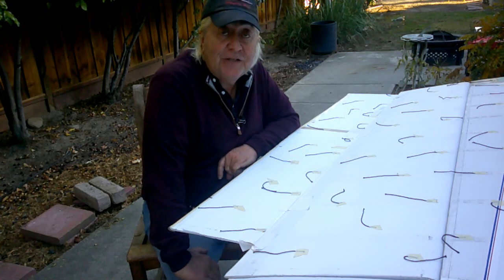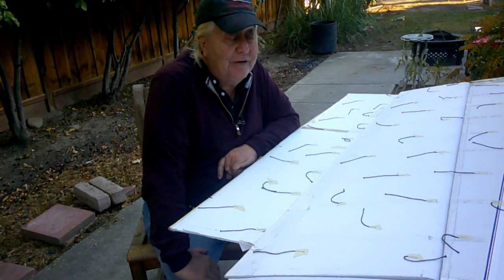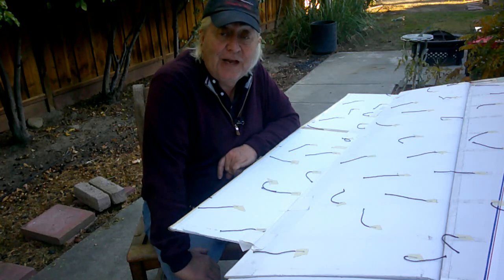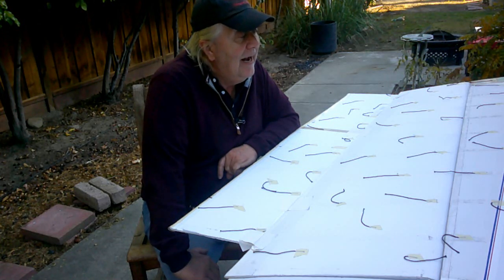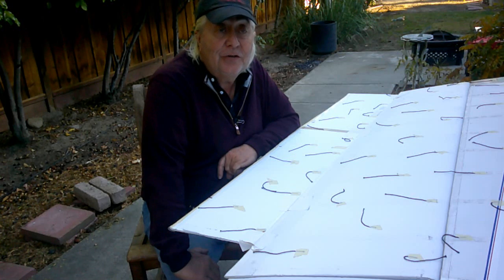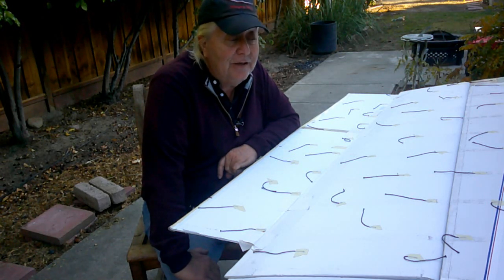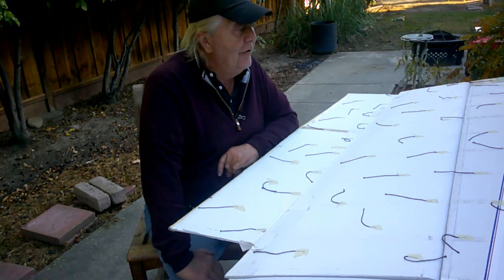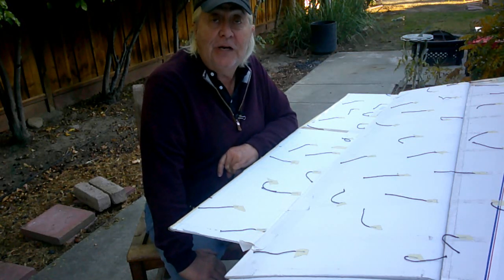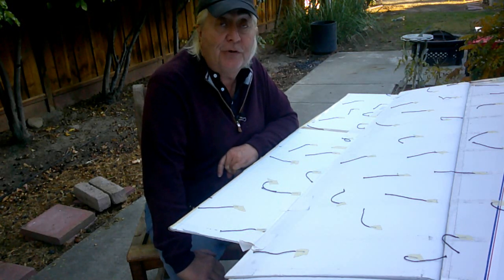There can be advantages to tapering it in terms of aerodynamic performance, but you can adjust for that with twist in the wing. And there certainly are tremendous advantages to having a constant chord wing when it comes to building it. All the ribs are the same. I don't need two separate molds for D-tubes. I only need one mold, same D-tube both sides.